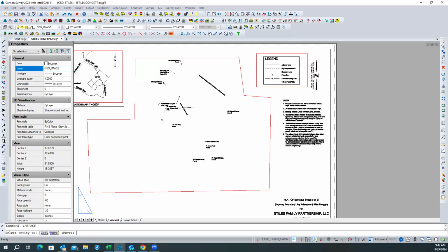See, this is when you label things like this in your drawing. If you label them in paper space, and then that model viewport shifts or moves or you rescale it, none of those point to the right things anymore. That's what I call the difference between annotating and labeling. When you annotate something and you want it to stay in relation to where those geometry items are, you need to do that in the model space and let it show through.